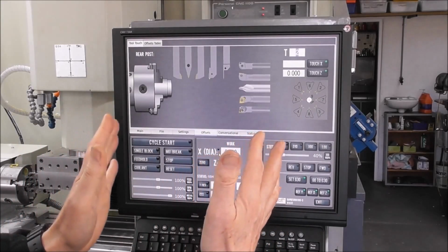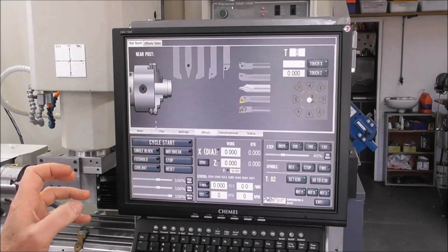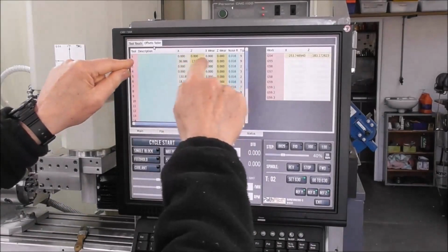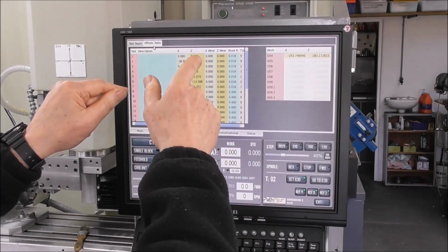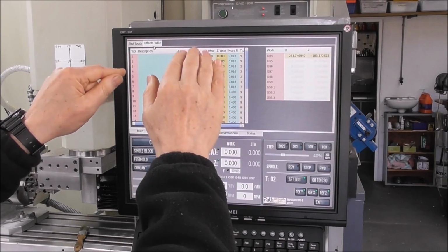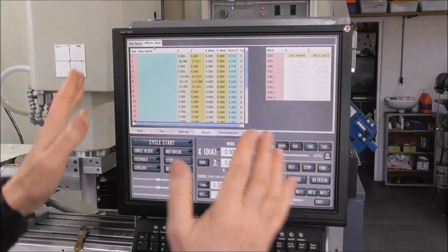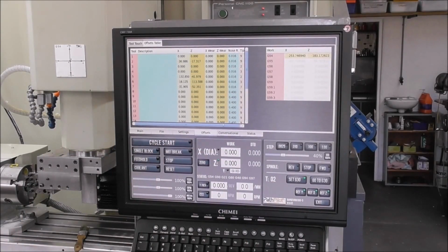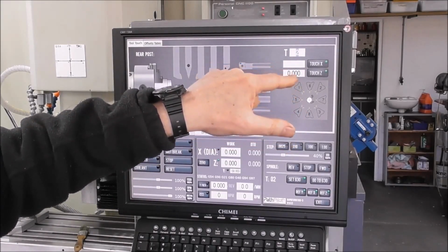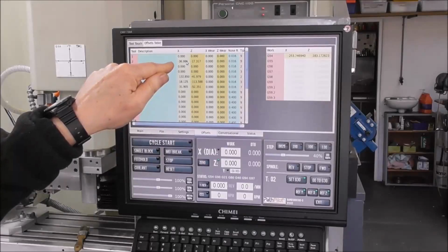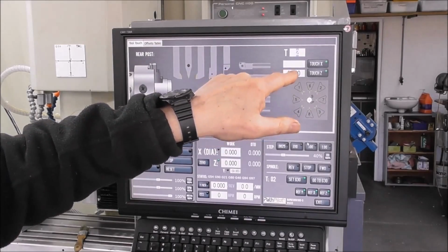And I think this is a concept some of us get confused over. I know I did in the beginning. We can think of all the tools in the tool table as all being tied by these offset amounts in the X and Y, and in the mill in the X and the Z, and in the mill X, Y and Z. But in the lathe it's X and Z. They're tied by those amounts, and if we want to change the relative position, then we must go and change it either here, which is a kind of a nice user-friendly facility, or we could actually enter it in here, but I wouldn't advise that. So we would change it via this facility.